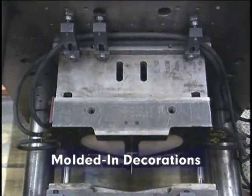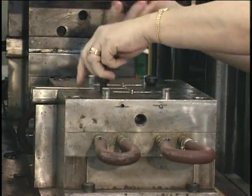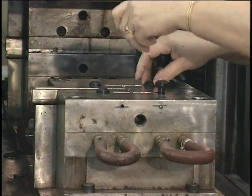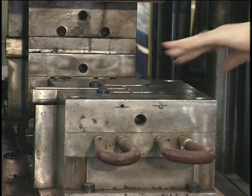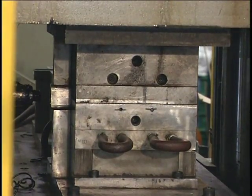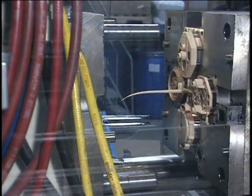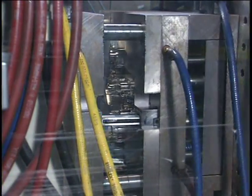Molded-in decorations are those machined into the mold, such as textures, or by implant, as with two-shot molding, where an insert is placed into a mold and then molten plastic is injected around the exposed areas of the insert, creating the part. Even pre-colored plastic resins are considered molded in color.